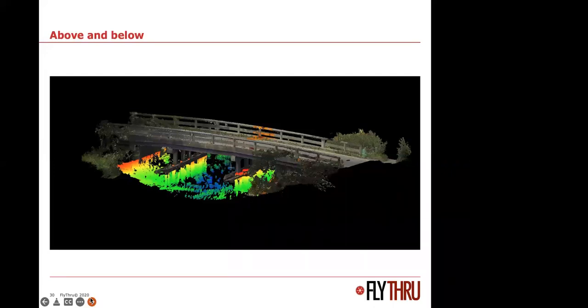And putting a diver in there is great, but a diver can't see anything if the water is mucky. And obviously there's a cost and that safety implication of putting a diver in the water. So we use an underwater sonar camera, laser scanning, photography, photogrammetry and LiDAR to build 3-dimensional images of the bridge, both above and below water. So remote sensing being used at its maxima there.